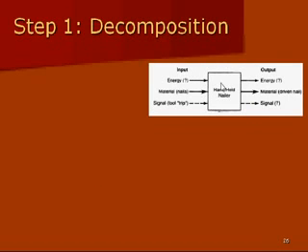So you can break down the nailer into three categories of inputs. And this is often a good way to break it down. You can trace the flow of energy, the energy coming in and the energy coming out. You can trace the flow of material. You've got nails coming in and you've got a driven nail going out. And then you can track the flow of information, the signal coming in and the signal coming out.